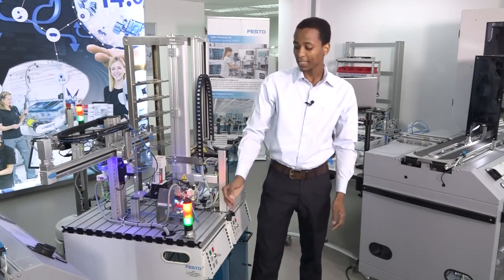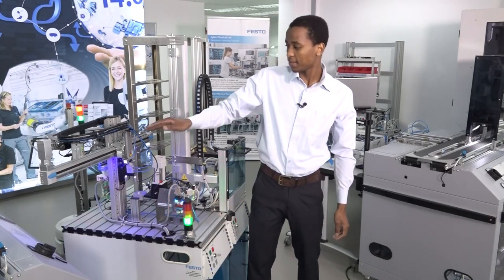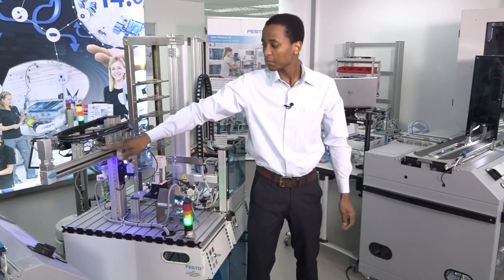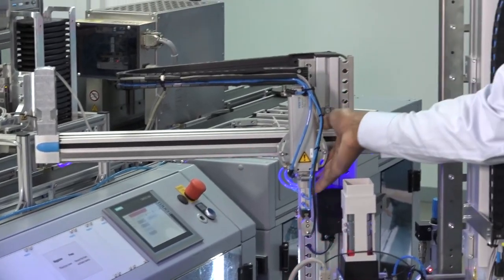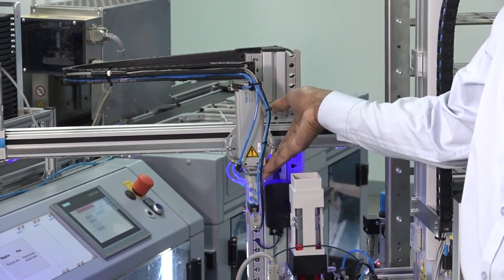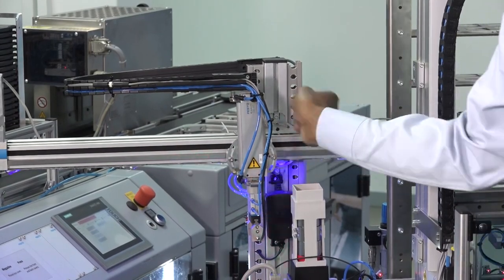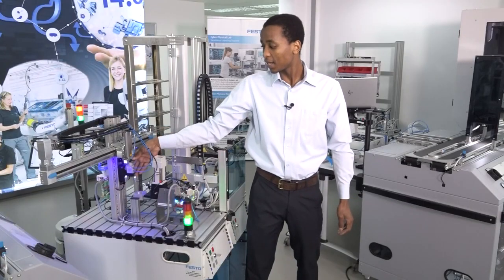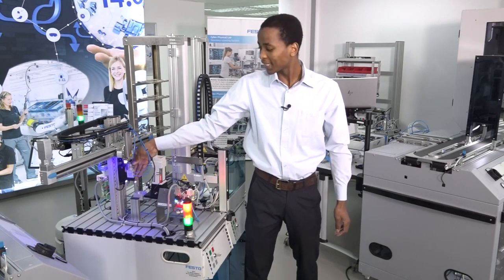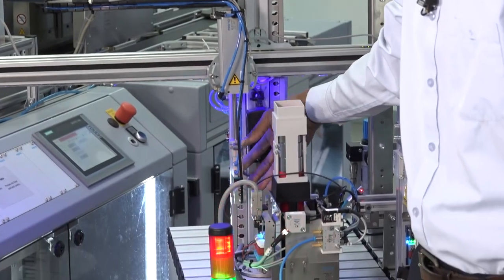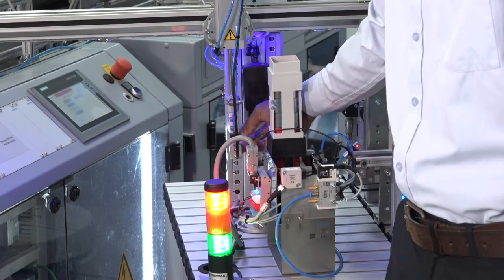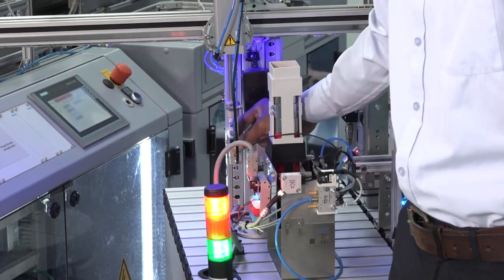The handling station usually consists of 3 parts. As I said earlier on, we have the control panel, and we have the electric drive, which is here. This is the gripper unit. So this is a double-acting cylinder that allows the extension to happen. The double-acting cylinder basically extends the gripper so that the gripper will be able to pick up the part. And this is the gripper over here.